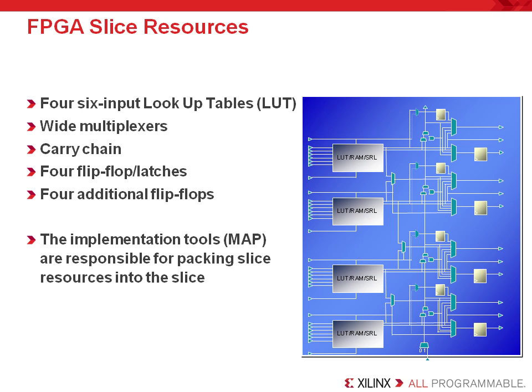Each slice contains a 6-input LUT that can also be broken into two 5-input LUTs. This allows the resource to be broken down if necessary to help assure maximum device utilization. Every customer must understand the input limiting nature of LUTs because many customers are used to building with ASICs. It is important to understand that the HDL code you write needs to be optimal for the FPGA if you're going to get optimum speed and device utilization.